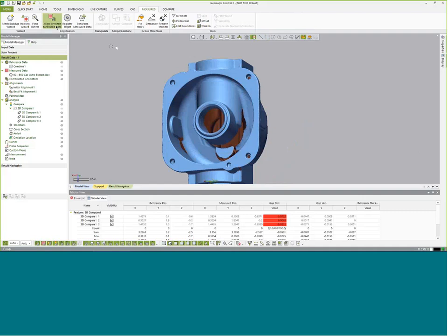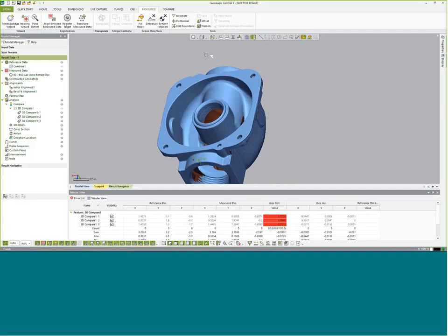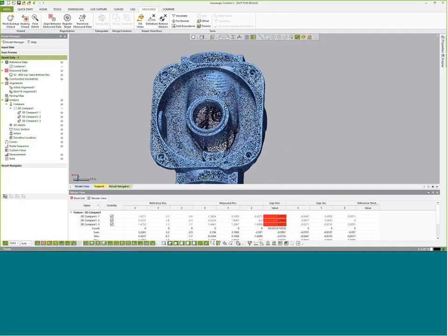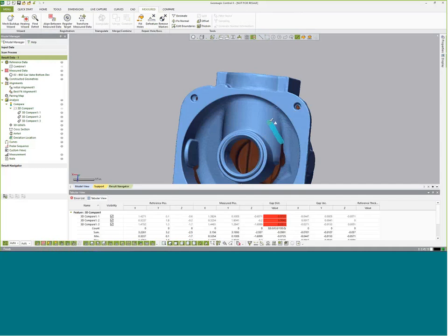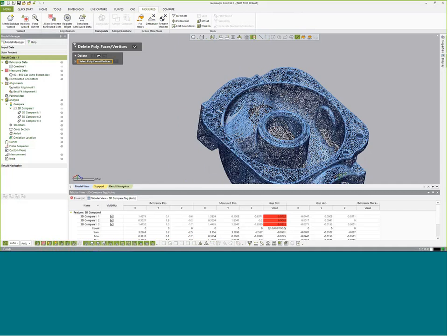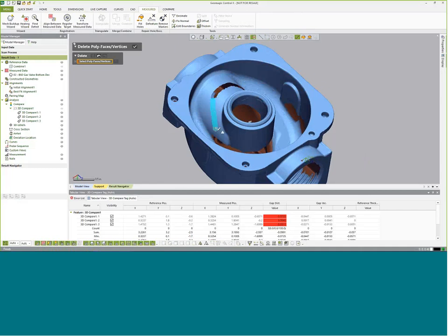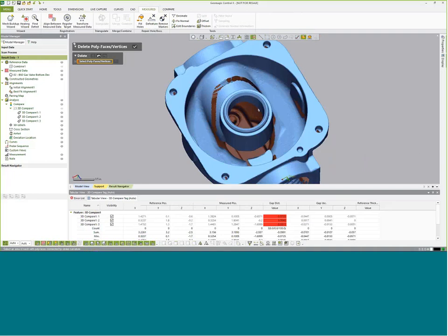So if we come over into our data tab here, as measured, we have a lot of features you'll recognize for line between scan data, filling holes, we leave a defeature in, stuff like that for maybe getting rid of some stamped on items or something that we may not want on our CAD model. We can do those things still in here, clean up our meshes. So what I'm actually going to do is come in and just highlight some of my data here of some things that I might want to get rid of. So for the sake of the demonstration, I'll pull out some of this data here, and I'm just going to pull that entity out in the center because it's just not on our CAD. It's just a red blob on our color map if we don't exclude the data.